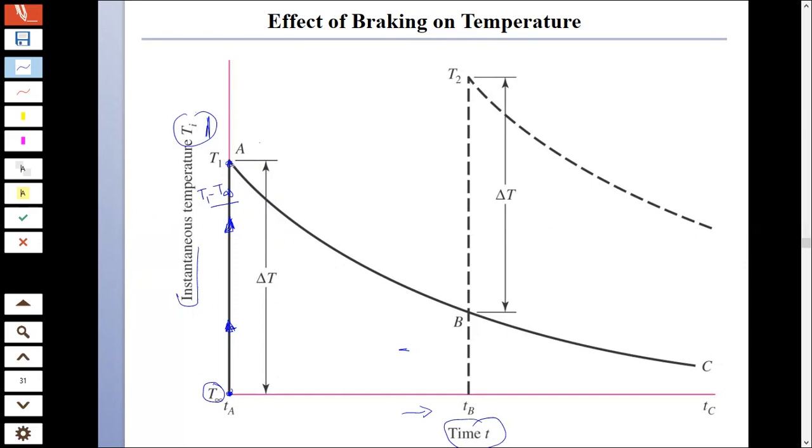With the passage of time, heat is going to transfer, and the brake or the clutch is going to cool down, right? Until you happen to apply another brake, or if you do not, then it is going to cool down to some temperature over here. But generally, you might need to apply a brake or a clutch. If you are moving in a car, you do that frequently, and your temperature is going to go up to T2, right?